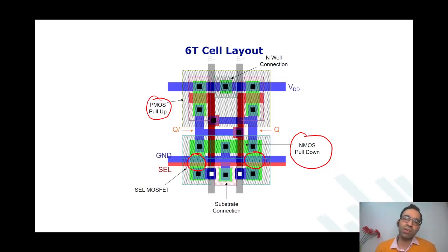Why do you think this layout is not acceptable today? Who can tell? Lots of empty space and non-symmetrical a bit. It is symmetrical. They are using vias on each contact. So many vias. We also use lots of vias and contacts. That was needed. Maybe lots of turning, lots of bends. Really, look at this. This poly is bending.